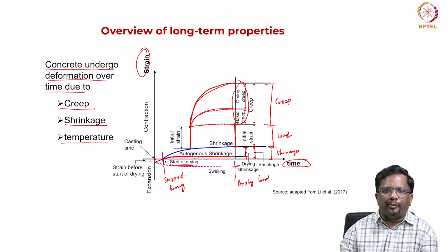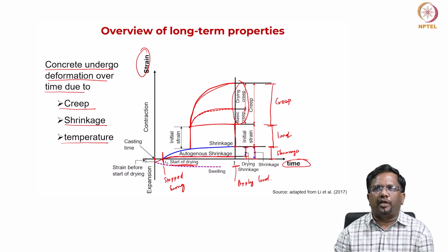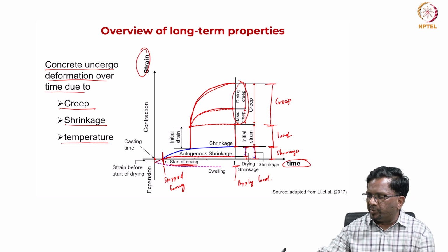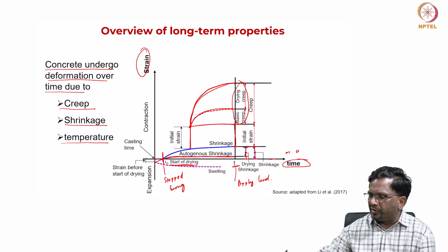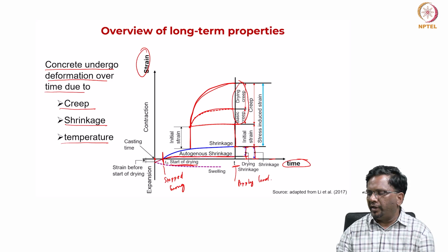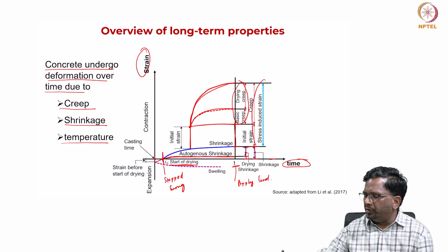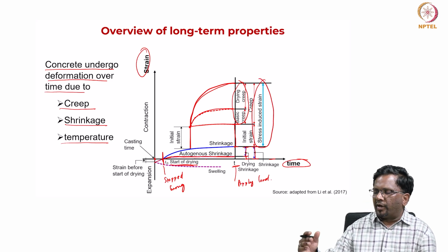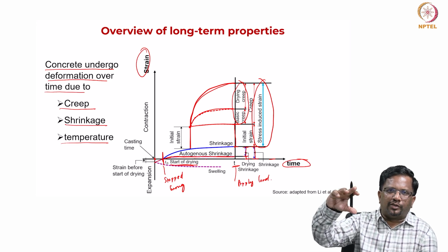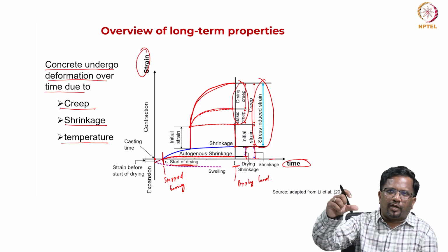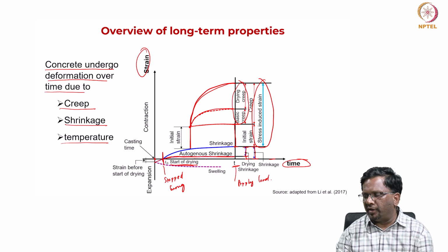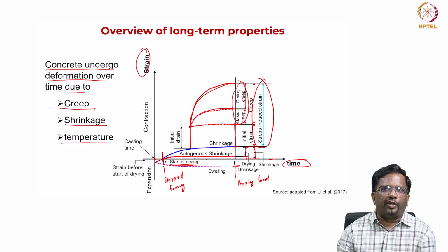So, you can see here creep strains can be much higher than that of load induced strain as well. That is something we have to keep in mind, especially in pre-stress, because you put a lot of stress in concrete, and the creep can be quite significant. That is what we call the stress induced strain. Whatever is because of the load, plus the load remains constant and then the creep strain is evolving. So, that initial strain due to load plus the creep strain, when we add them up, that is the total strain induced by the stress.